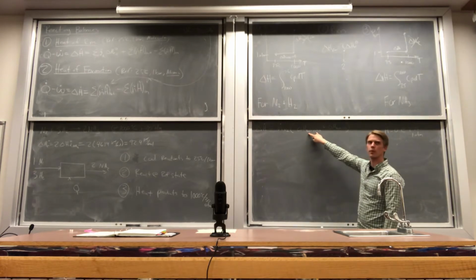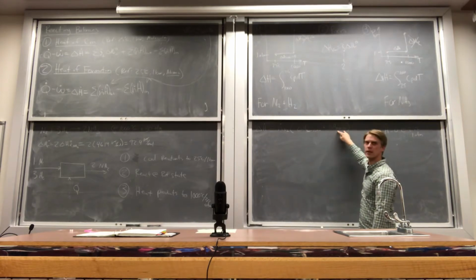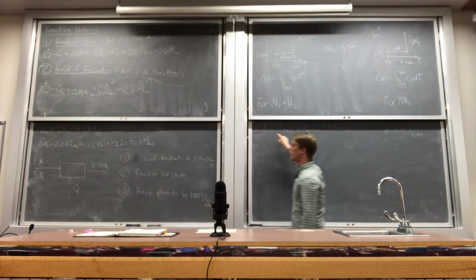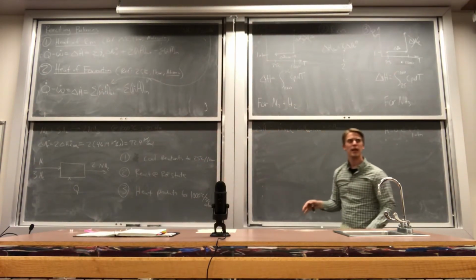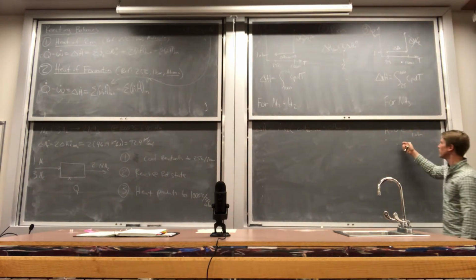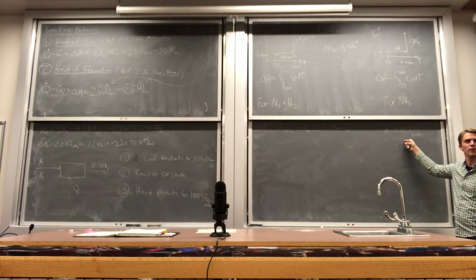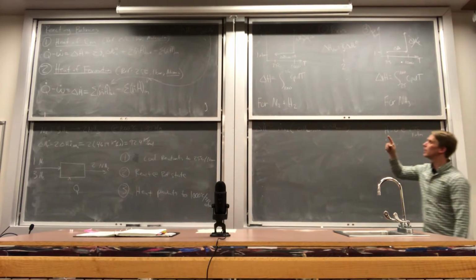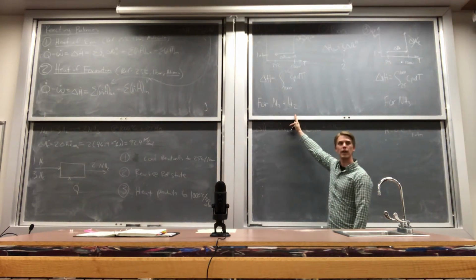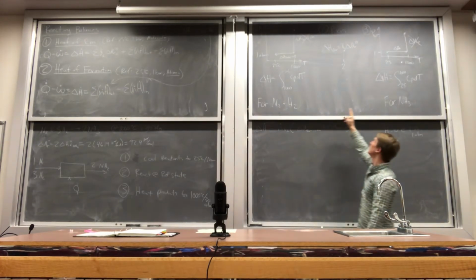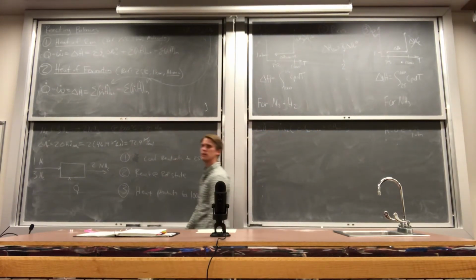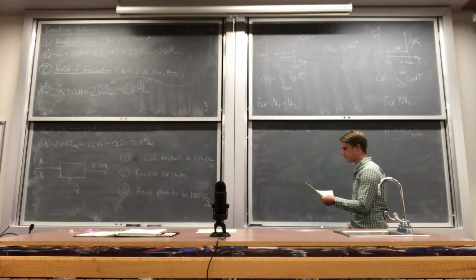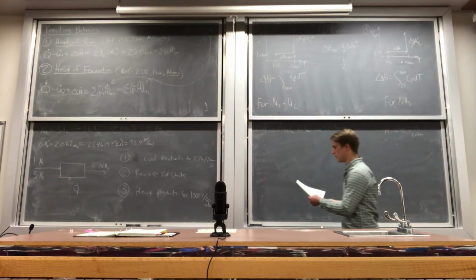So if I'm going from the reference state to my actual condition, then I would be going from 1 atmosphere to 30 and from 25 to 1,000. So that's why this should be a negative, like it is in that equation. But I did the opposite approach. So it actually all works out algebraically, but I just realized that my example problem is opposite of what the problem is here. But the case holds true. The same thought process is what we're actually doing. We're actually cooling everything down to the reference state, reacting it, and heating it back up. But based on how we define the reference state here, I've got the pluses and minuses switched around. Only for the feed. For the outlet, it's exactly the same. I did it right for the outlet.